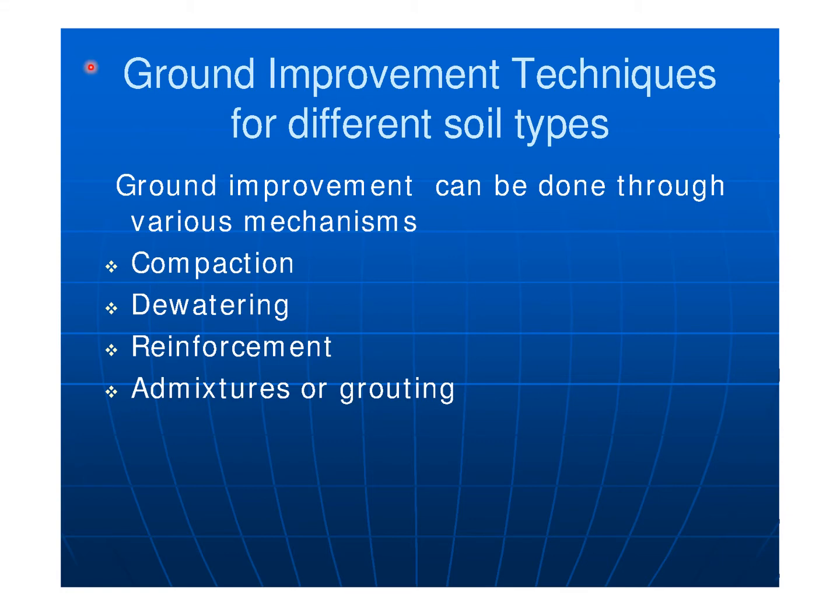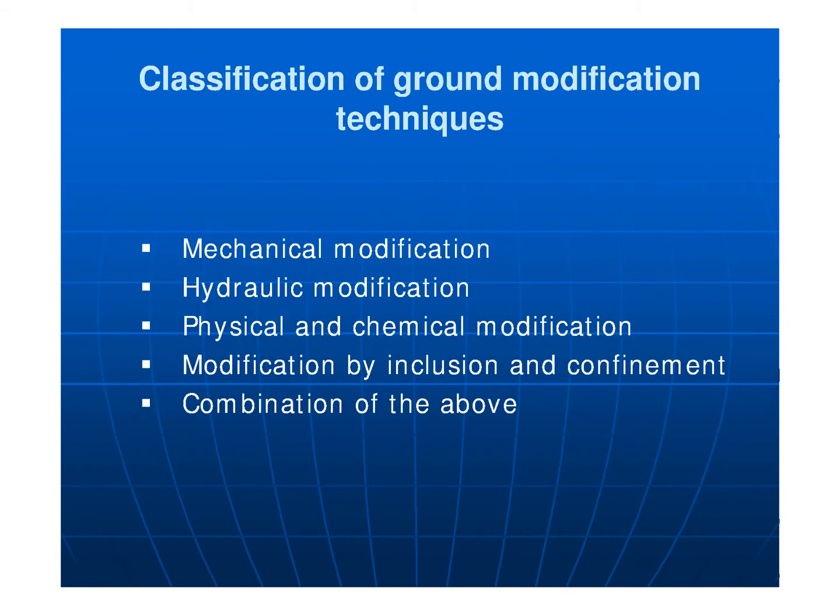Ground improvement techniques for different soil types. So we are having different techniques like compaction, dewatering, reinforcement, admixture or grouting. Classification of ground modification techniques: mechanical modification, hydraulic modification, physical and chemical modification, modification by inclusion and confinement, combination of the above.